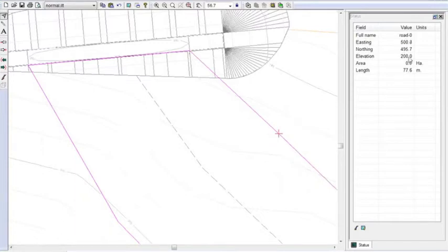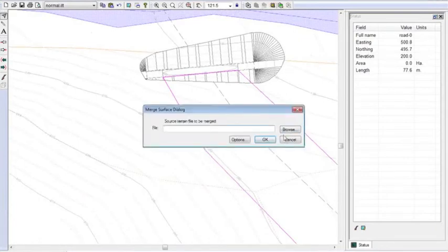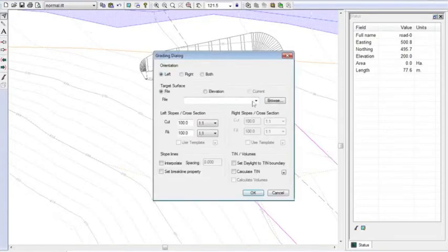It's 3D. It's at the right elevation. And the surface that I'm going to grade down to is now containing the wall. So let's do that. Grade to the surface. Whoops, wrong one. Grade down to that surface, which is the background. And again, I want to do this one. Ooh, it's clockwise this time, so I want to go to the left. Maybe I'll use 1.5%, or 1 to 1.5, or 67%.